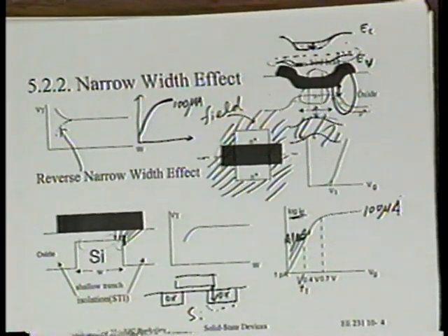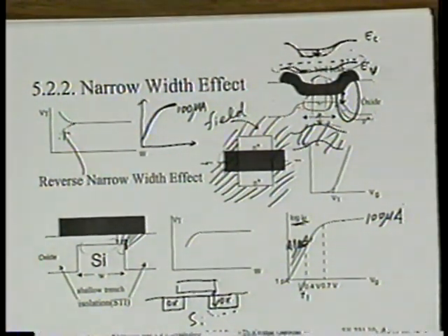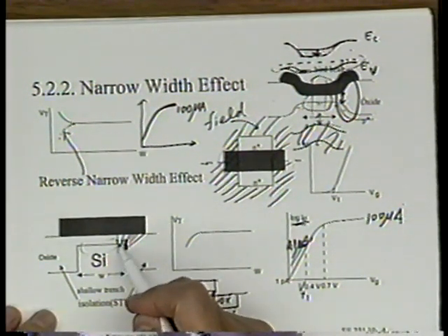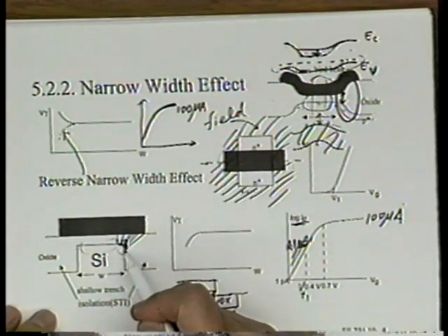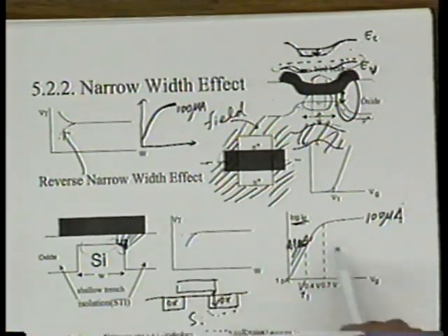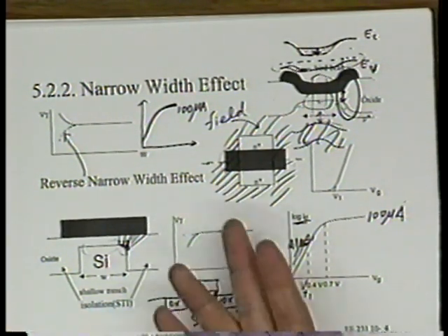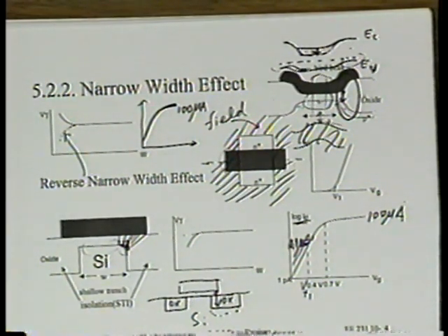And in fact, what you just asked gives me a very good opportunity to say something for the experts in the audience. There are probably experts who will say, gee, but we know that by making this corner smoother, we can minimize the thinning of the gate oxide, and that's a standard technique. And by doing that, we also end up fixing this VT roll-off problem, by fixing this narrow width effect on the VT. So why do you say that thinner oxide is not the culprit? Because I know by making the corner smoother, the oxide is no longer thinner, and VT is no longer falling off. Then why did I say that the VT falloff did not result from the oxide thinning?